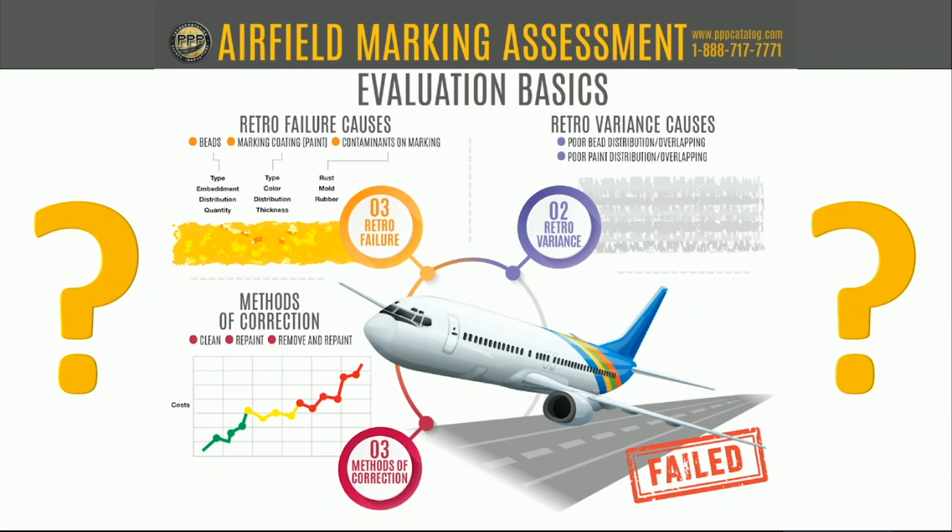And then if we do decide to go with a more durable material like a thermoplastic or a tape, now I'm really curious, Mike, you can answer this question, I'm sure, what we do is we inlay that material. If it's a 100 mil product, they'll grind about a 125, 150 mil groove in the road, and then they'll inset that material, which provides an incredibly long and wearable material that's not affected by snowplows. Mike, what do we see in the airfield?